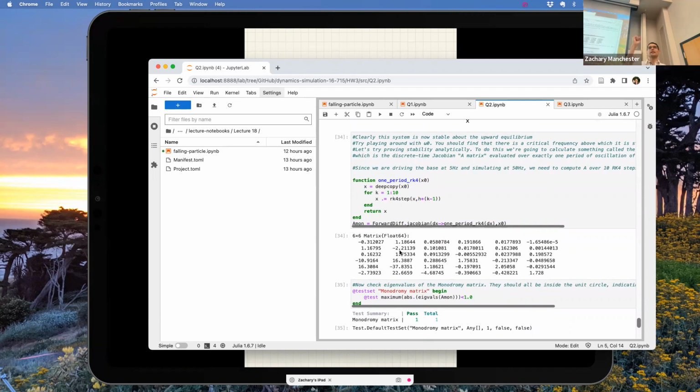Normally when you do this, you take an equilibrium point, you linearize, take the eigenvalues, right? We've talked about this. Here it's a little weird because it's shaking up and down, and this is a periodic motion. And it turns out what you have to do is basically linearize the full period motion around one full period of shaking to get this to work. For a periodic system, this is called the monodromy matrix. So it's like the discrete time A matrix around a full period. This is a good little thing to know about.